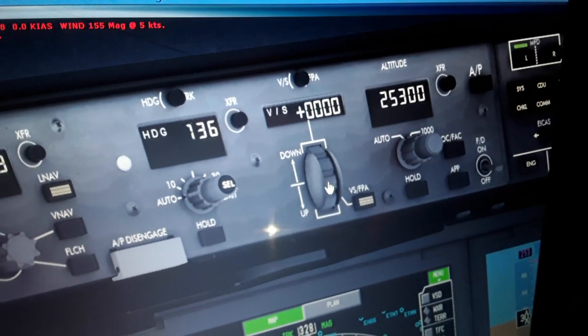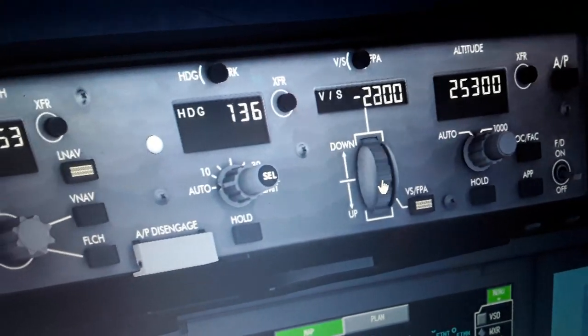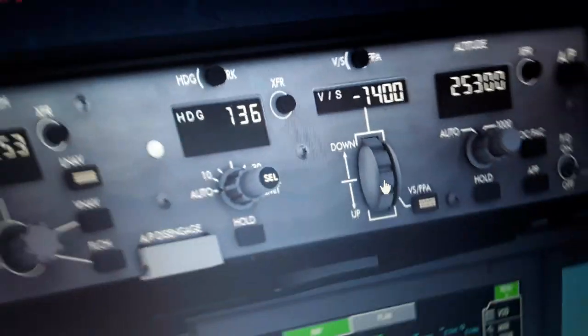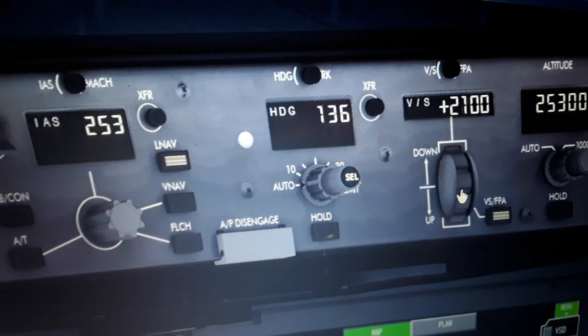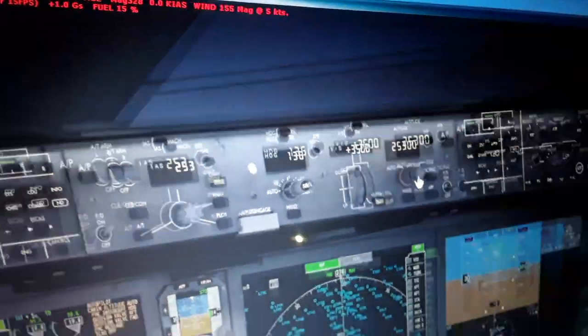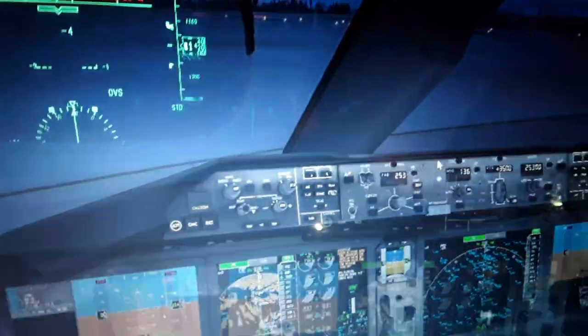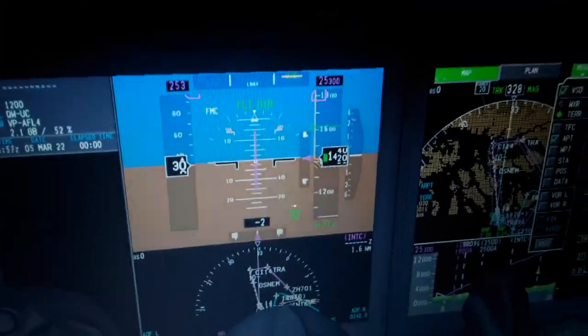And we have the vertical rate of descent over here, or the flight path angle. You can see a minus sign is a descent. Level off is zero, and a climb is like 3,500 feet per minute. You will see everything displayed. We have our localizer and approach for autoland function over here, airspeed and altitude selected.